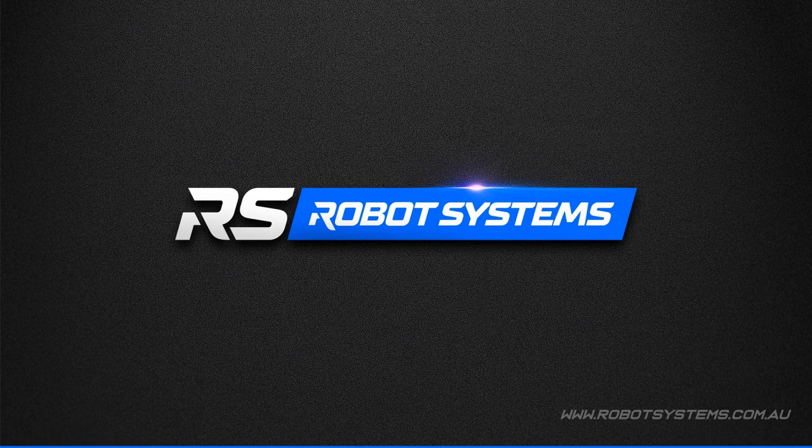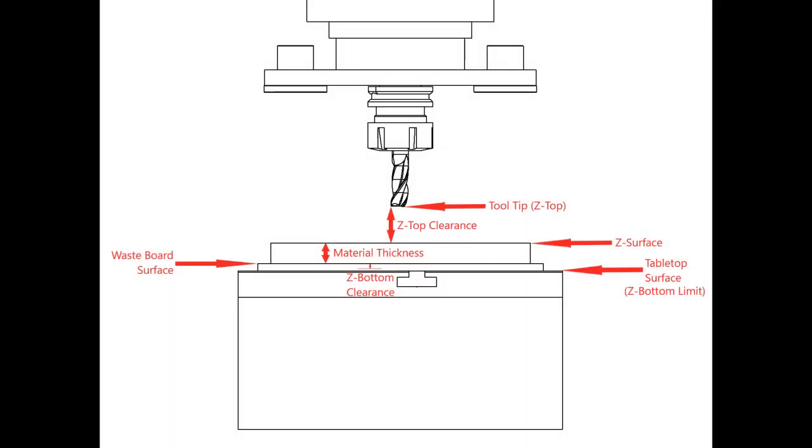Welcome to the Robot Systems tutorial on initial Z settings. The initial Z settings are settings that aren't set on a daily basis. These Z settings will include the Z bottom limit, the wasteboard surface, and the calibration surface.